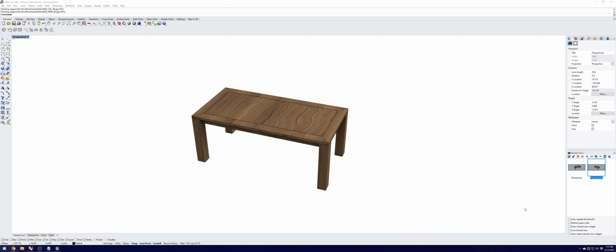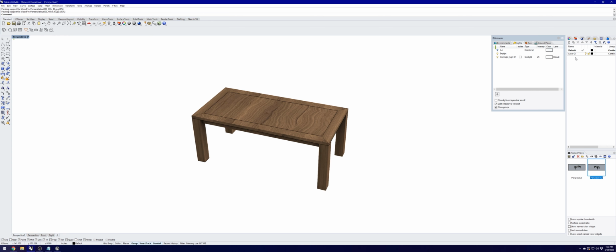So let's get started. The first thing that I want to mention to you guys is the naming convention of your layers and blocks within Rhino. Typically when you create a new layer or a new block and you're typing in the name, you're going to want to put a space in between the two words. Unreal Engine doesn't really like spaces between words.